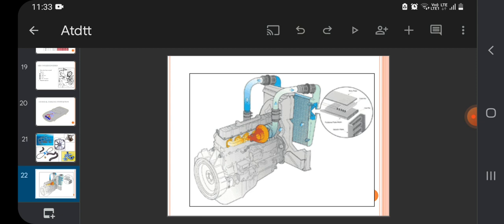As in the air there is no water supply to cool the engine, it is called an air cooled engine system, as only air is responsible for the cooling of the engine. Here also air is drawn by forced convection, or the outer body of the cylinder container may be designed in such a way that it feels more drag in the air and gets more contact with the air, which in turn absorbs the heat from the engine and reduces the temperature of the body of the engine, which results in smooth run of a vehicle.